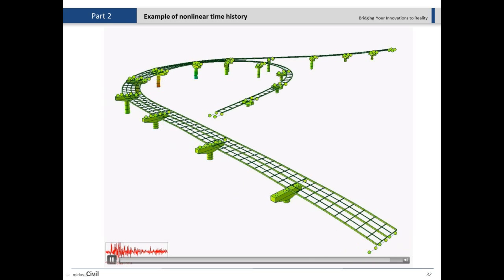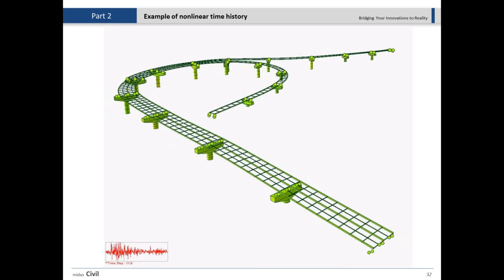So we can simply follow, if you use MIDASoft, I took this video from MIDASoft. When you're applying the plastic hinges to the column, you can exactly follow the columns, and you see that at a different level of the forcing, if any of those columns or any of those plastic hinges are formed, and then you have the failure of the structure. So that's pretty useful in this way.